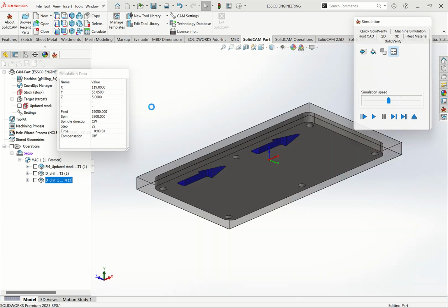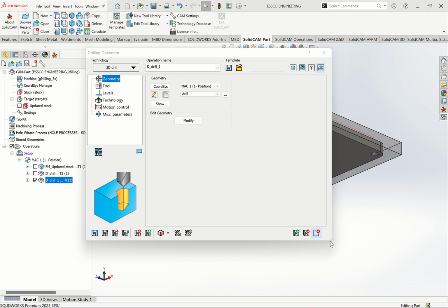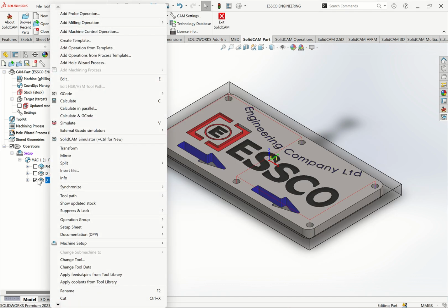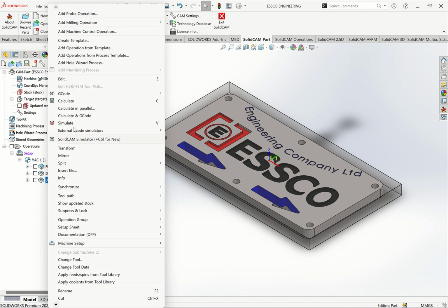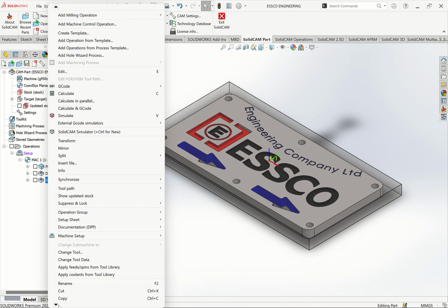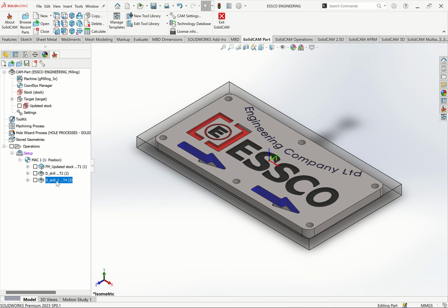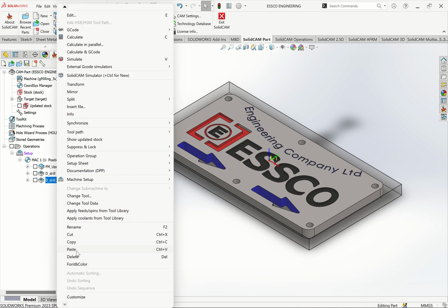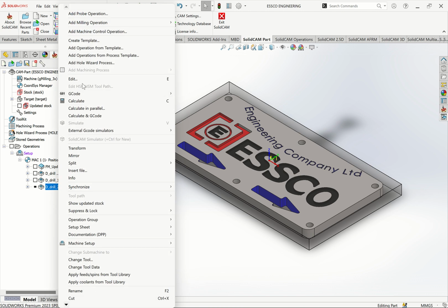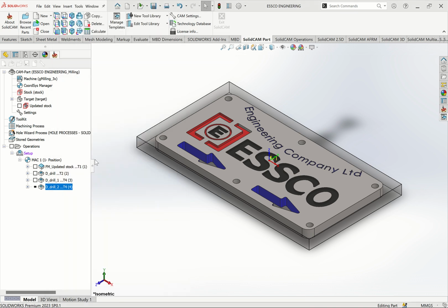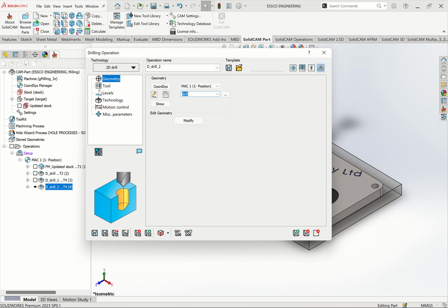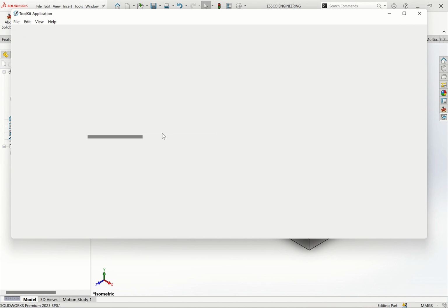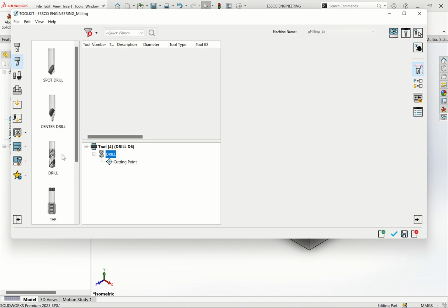Okay, so that is for what we have used, 6. As I said, we want to use M10 by 1.5. So next is again copy the same program, copy this second one, scroll down, copy, then right click here, go down, paste. Shortcut way of programming. Then click this one, edit. Now the tool we want to put to be 8.5. We will do the same here. Change the tool now to be 8.5 here.